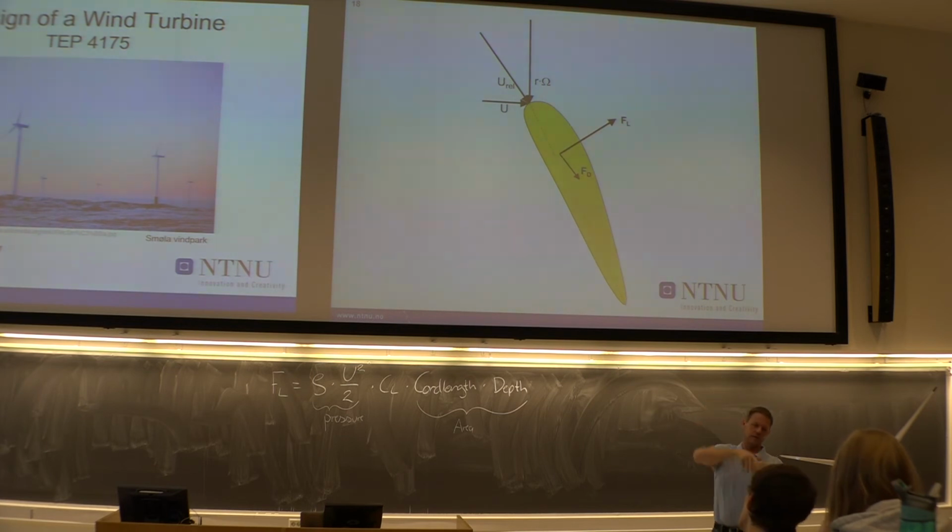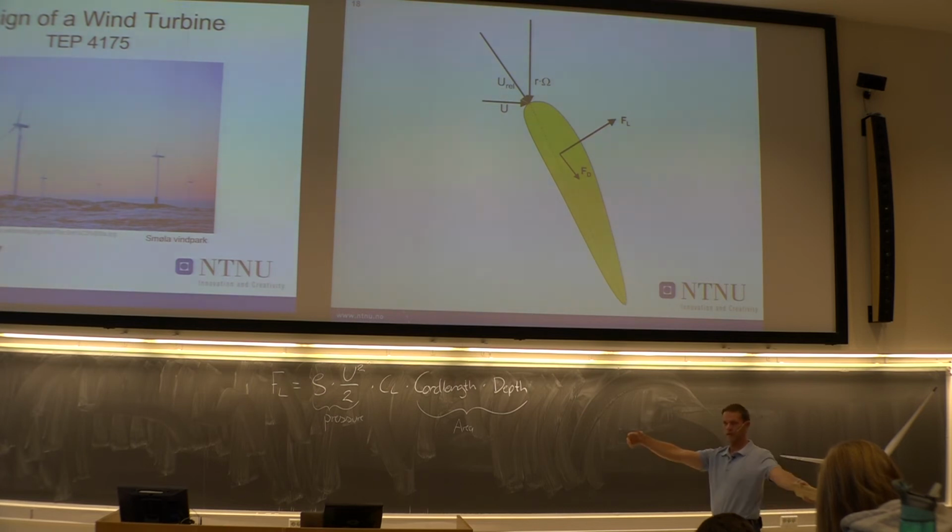So because of the rotation, that wind component is coming towards the leading edge of the blade. And then, of course, the real wind is coming normal to the surface of the rotation. The relative velocity will be just the diagonal of this triangle.